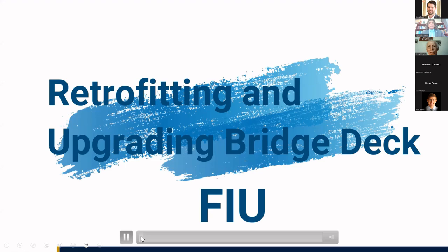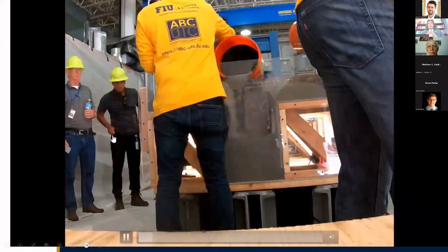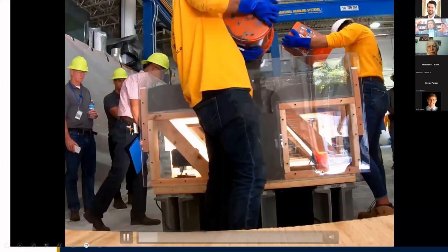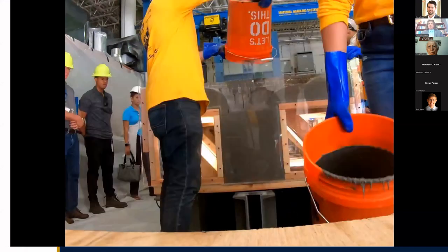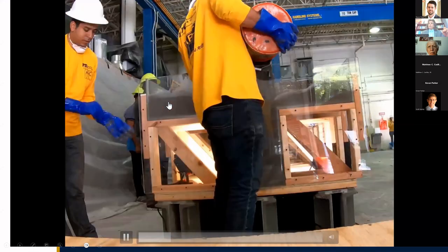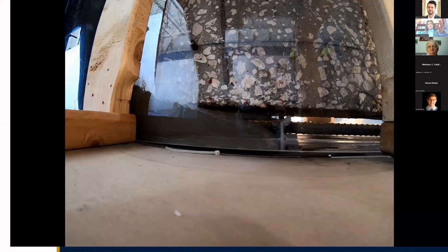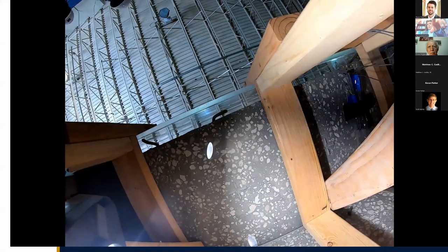This is a test that we did. We put a T-beam made of concrete, and then we added some reinforcement. We put it inside the epoxy glass formwork because we wanted to see how the UHPC flows around it. And you can see over here how well it is flowing. This is the bottom of the T-beam. See how smooth it is. In fact, after we removed the epoxy glass, it was like glass because we used the epoxy glass for the formwork.